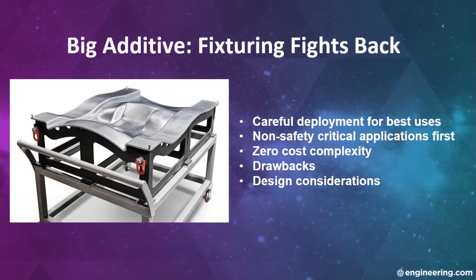An important advantage that we can exploit for large assembly work is the ability to use a smooth, polished, and hard-wearing top surface backed by a tougher but cheaper substrate. This can eliminate conventional post-machining surface treatments and plating, and the surface layer thickness can be tuned for the surface environment and the expected life of the tooling.